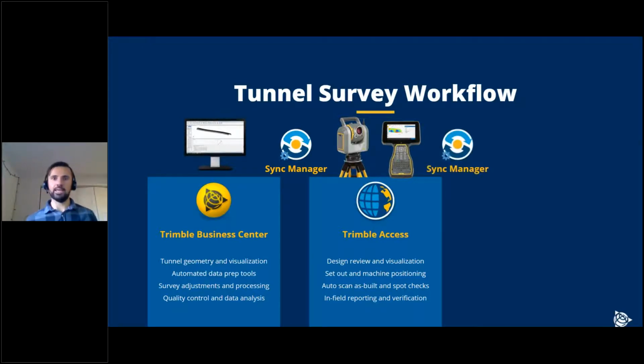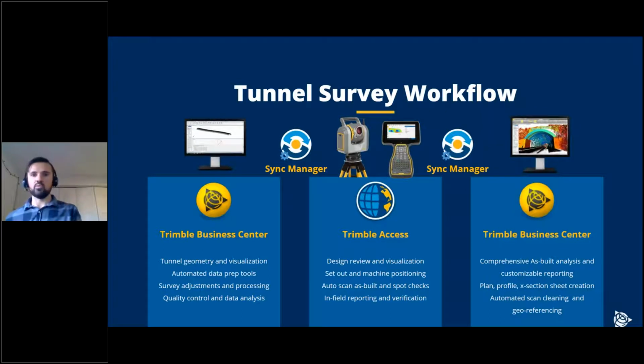And once you've collected all that data, for more of the comprehensive analysis, more of the reporting and deliverable piece, bringing it back through TBC. Same thing, all of that data comes seamlessly into TBC, whether it's survey data from the total station, whether it's level data or scan data from something like the SX12, all sits in that one environment. And we can generate a variety of different reports like as-builts, customizable reports, whether it's an as-built report, inspection report, whatever it might be. You can change up the layout, you can add your company logo, whatever you want to do with it, and still get all of that data that you need from it.